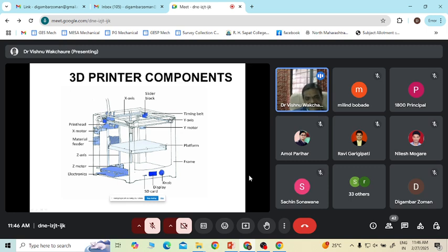In case of metal additive manufacturing, when you are either diffusing or melting that particular powder, there will be chances of heating. The temperature will increase, then oxidation and all these things. So in that case, you have to have this particular environment as a controlled environment so as to avoid oxidation. So metal additive printing will be done in an inert gas environment. You will be using argon or helium or those kinds of inert gases, so as to avoid oxygen.